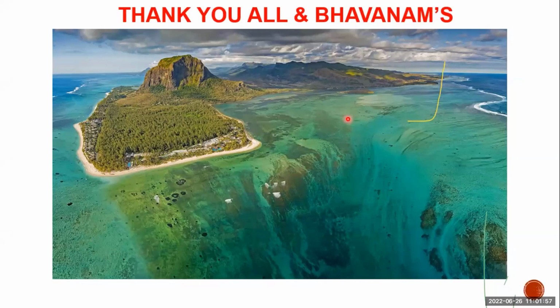When I was doing my internship at a mining site, they were using the falling head test, because the ore was only 1 meter below the ground level. Actually, with the falling head test we calculate the in-situ permeability, maybe they want to check that.